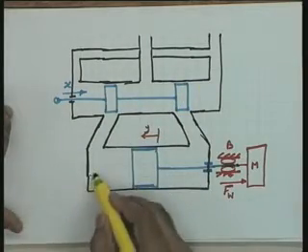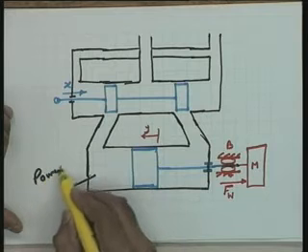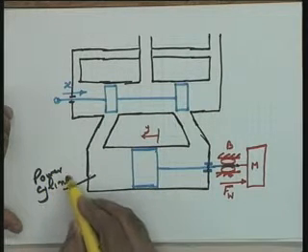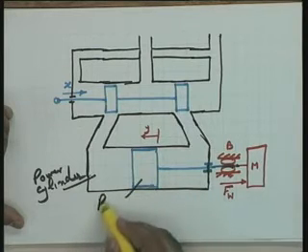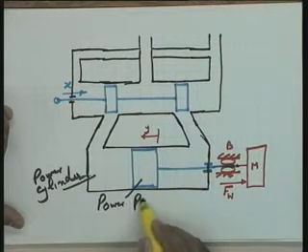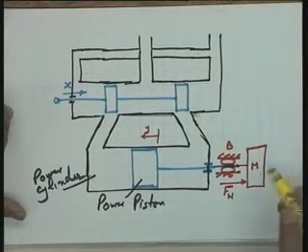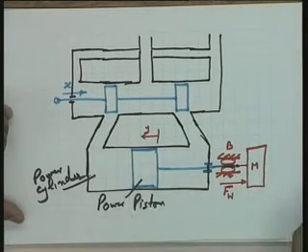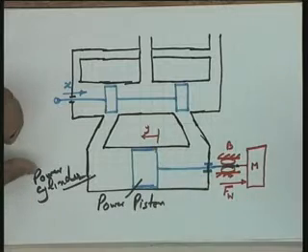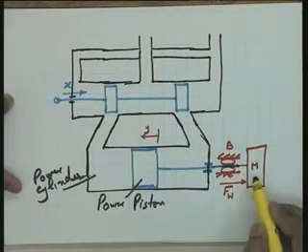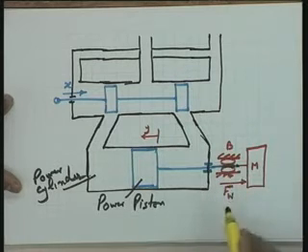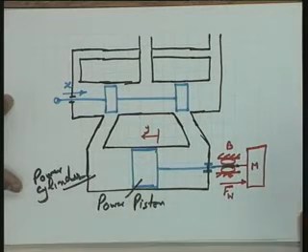I say that this is your power cylinder. Why the name power cylinder given to it? Because this cylinder creates the motion of this particular piston, the power piston, which is going to move the load. Here is the load which requires a linear motion, and the linear motion of the load is given by y. The basic parameters of the load I have taken over here as m the mass, b the viscous friction, and Fw as a disturbance on this particular load. The parameters are equivalent to what we have been discussing in the earlier systems.